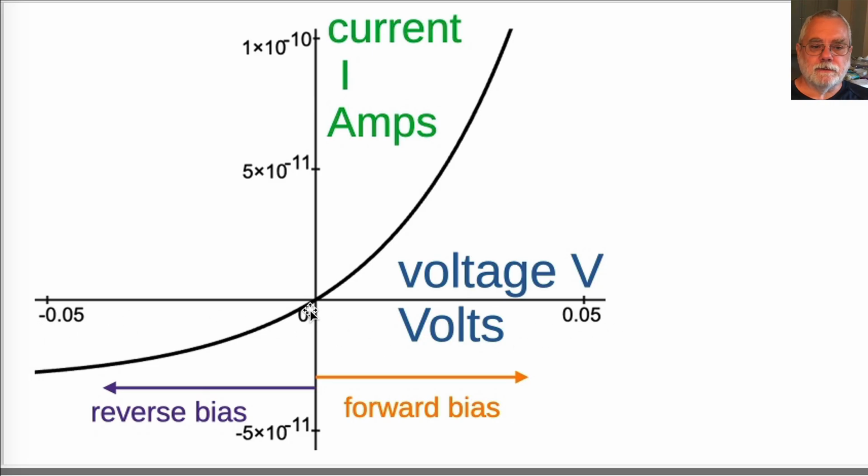At 0 volts, the current is 0. For positive voltage, the current into the p-type anode contact is positive. For an ordinary diode, this region, the upper right quadrant, is generally called forward bias. We'll cover solar cells in a bit. For negative voltages, the current with this convention is negative. The lower left quadrant is called reverse bias.